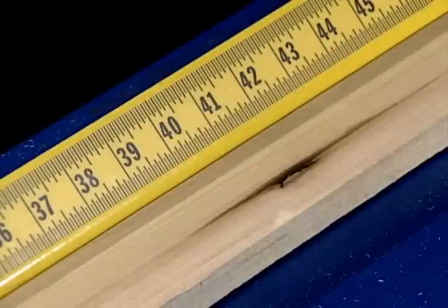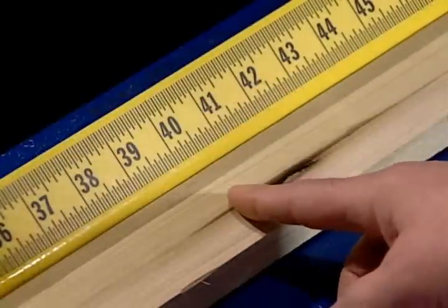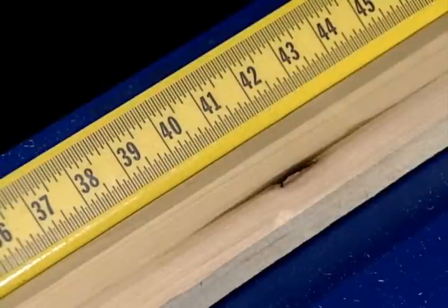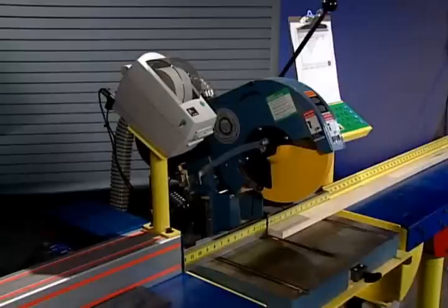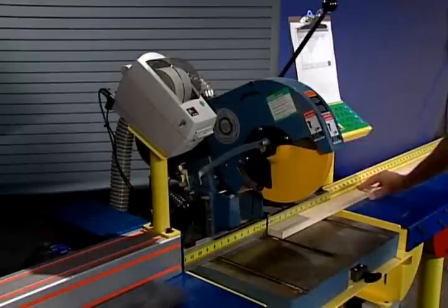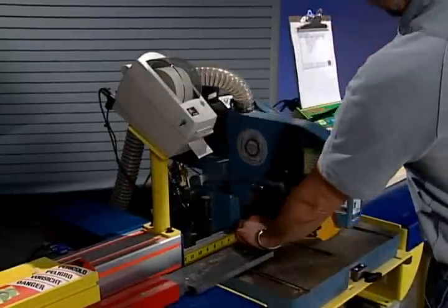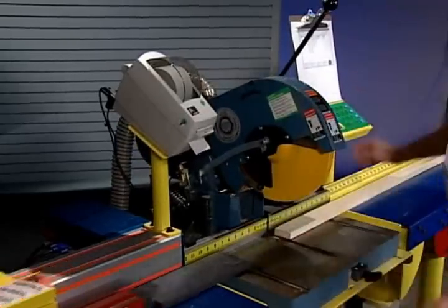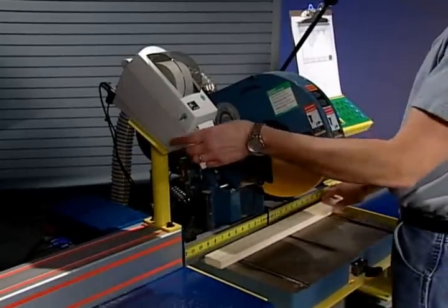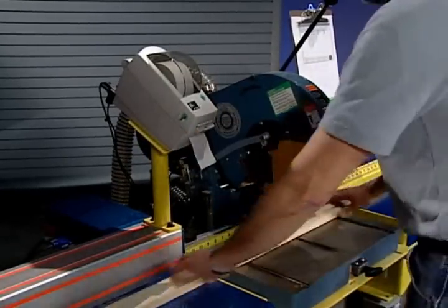After the defect is removed, Ed looks for the next defect. There is another knot at 40 inches. Again, he enters the usable stock length into the controller. The Optimizer figures out the best use and the stop moves to position. Ed has finished the cut and it looks like the Optimizer can get more pieces out of the usable length.